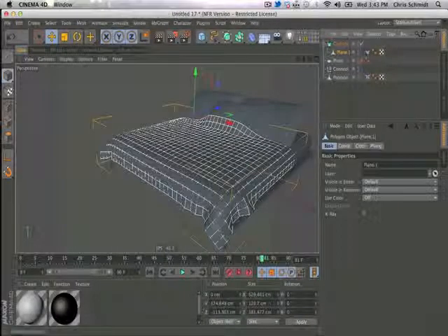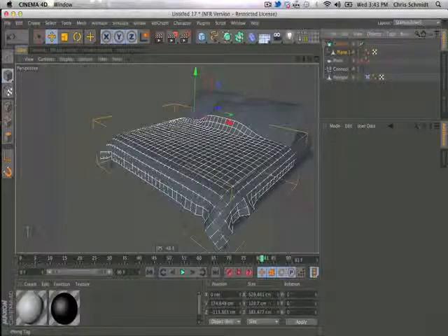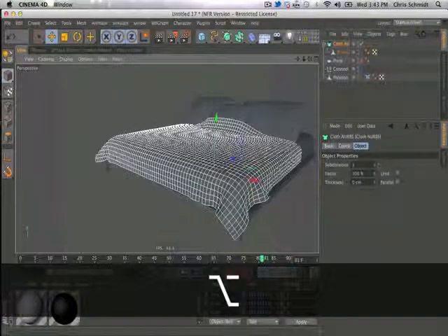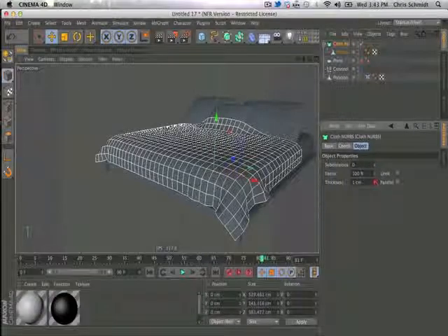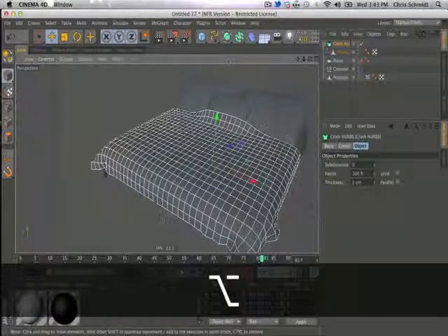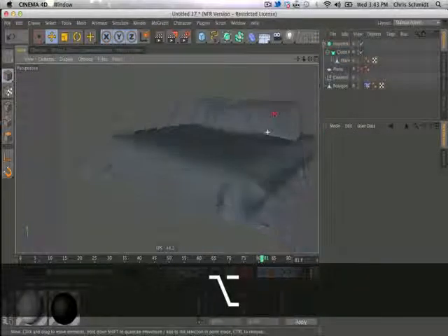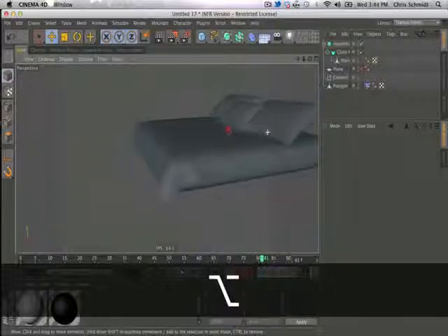So we can drop this right in the cloth NURBS. We don't even need this simulation tag anymore. So we got the cloth NURBS. We don't need subdivisions, but what we do need is some thickness. We get that thickness, and then we could even take a hyperNURB and drop that into a hyperNURB, and that should kind of smooth out our corners again. So there we go. Now we got a little blanket there. And yeah, that's all good.